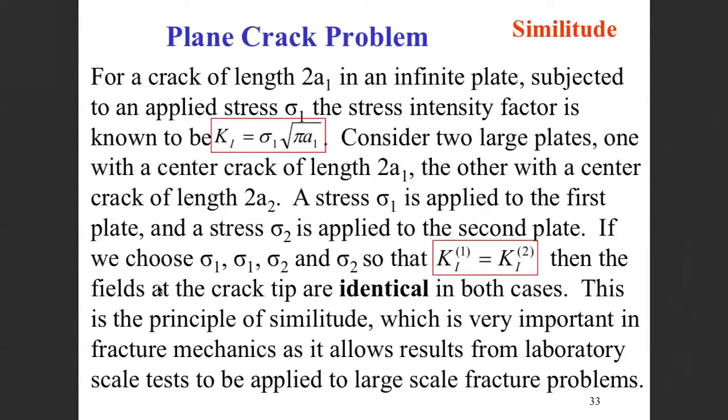So what I can do is then take, say, for example, my weird washing machine knob case and use stress and strain fields that are calculated for a plain crack in a flat plate, right? Because I just need to figure out what the loads need to be to get my stress intensity factors to match, right?